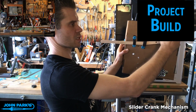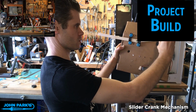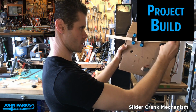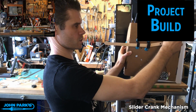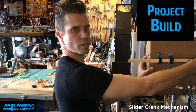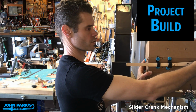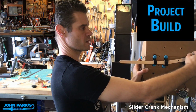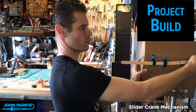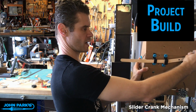So you can see as this rotates back and forth, move that a little bit more this way, it will turn into, whoops, you can see that, just the linear motion of that popsicle stick. So this is one way to transfer the rotational force or motion of the servo into a linear force or linear motion on the end of that slider.